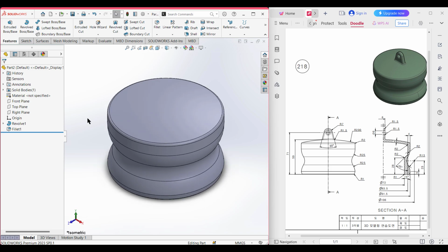Now let's go back to our sketch. In our sketch we can see that along this line to this line, it has a distance of 71 unit, and along this 71 unit distance it has a circular profile, and this outer circular profile has a radius of 7 unit. So from 71 unit distance I will draw a circular profile of 7 radius, and from the circle I'll draw an inclined line, and this inclined line from this center line will have an angle of 30 divided by 2, so it will have an angle of 15 degree. Then I'll mirror this angle here also.